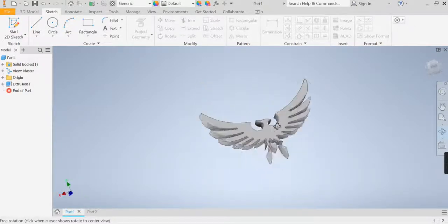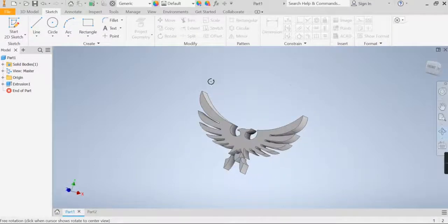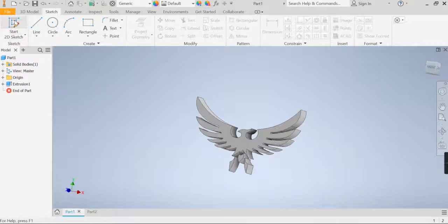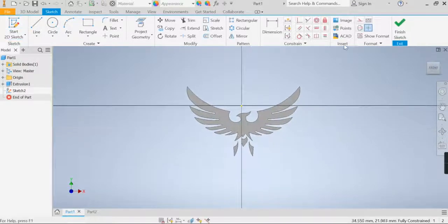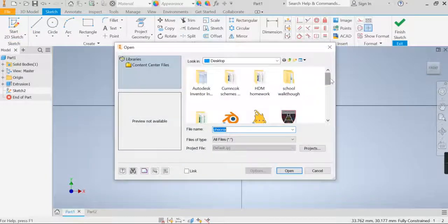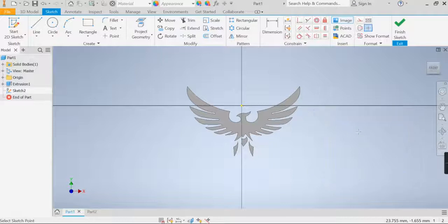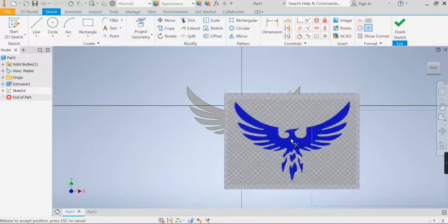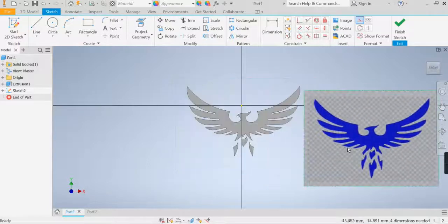Well done. Now, moving forward, to finish this task off, what we can also do with our image is start a 2D sketch on my object and insert my original image. This is how we are going to use our decal command. So let's overlay it. What you'll see is that if you bring your image in, overlaying becomes quite tricky because you can't see your object.